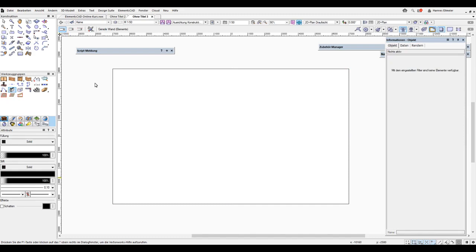In the method line, we have guidelines. If I take the third method clockwise, the wall is pulled downward because the mouse cursor corresponds to the red dots, and unfortunately, in ElementsCAD, we don't have a preview of the wall thickness, but the result is exactly the same.